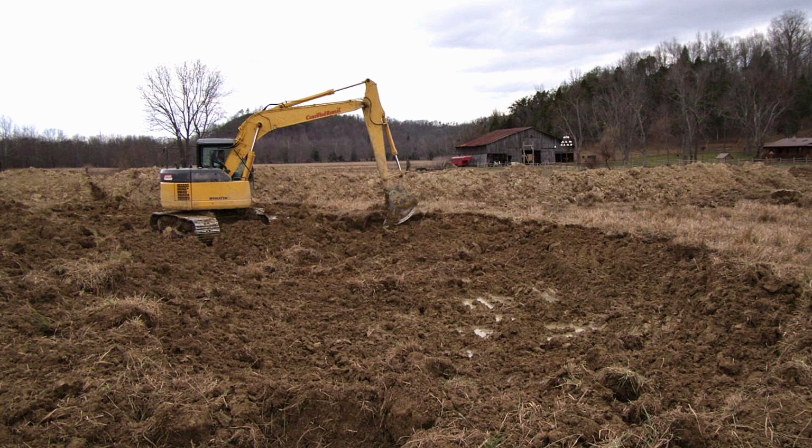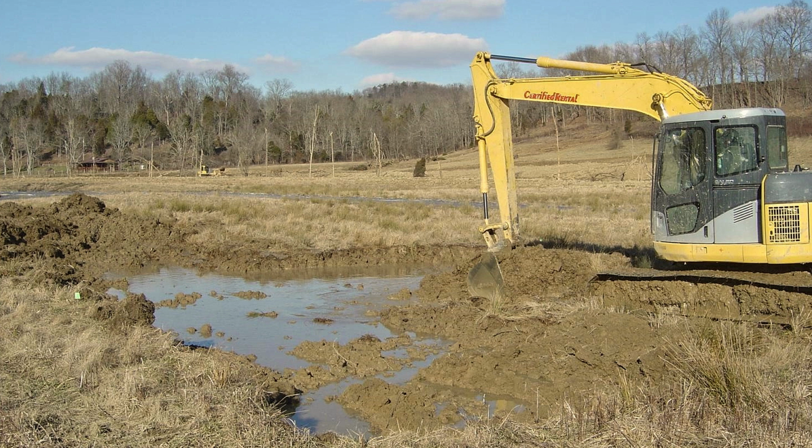Shallow depressions of various depths were dug over the field after the groundwater dam was completed to restore both emergent and ephemeral wetlands. The success of the groundwater dam can be seen by groundwater rising in the basin as it's being dug. Shallow water emergent and vernal pond wetlands with natural contours, including pit and mound topography, were restored in the large field that had been filled and leveled for drainage.